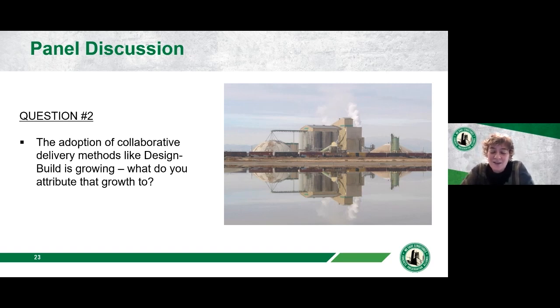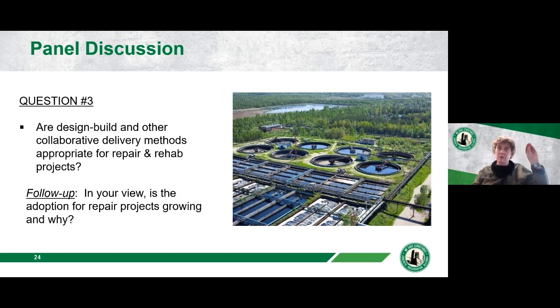But yeah, on the QA/QC front, a fundamental shift happens. It's still going to be that the QA is housed within the engineer of record, and the QC is still housed within the contractor side. But in the past, because the owner had the engineer and then the contractor on separate contracts, the contractor was handling the QC side, and the engineer that the owner had hired was handling the QA. In the shift to this new design build world, the design builder team is handling both QA and QC.